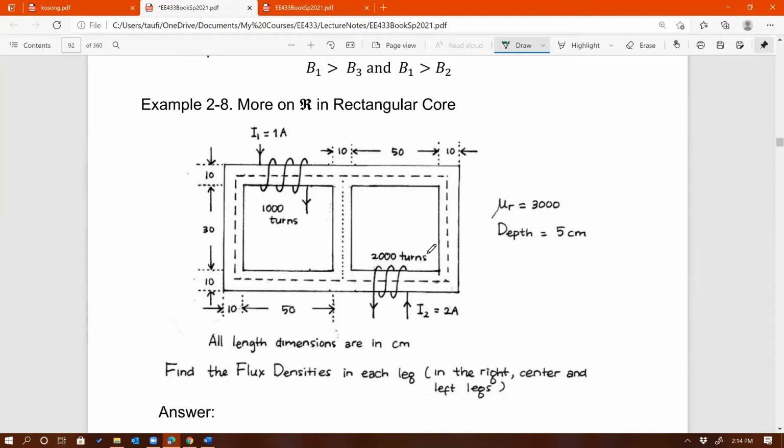Even though the other side is voltage, not current, if you apply current here, then you're going to induce voltage there. If you just leave it open, of course there's no current. But if you connect a load, it's going to draw current, and that current multiplied by the number of turns gives you another MMF. Makes sense, hopefully. So that's the case when we have a transformer.